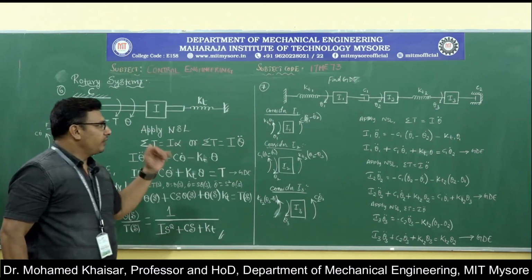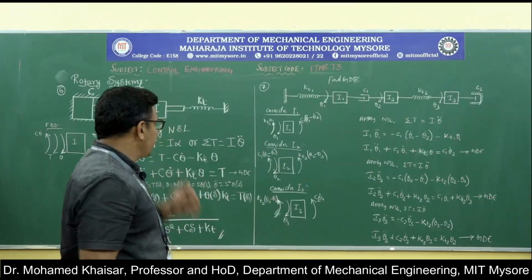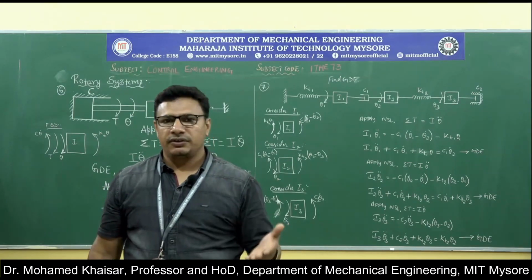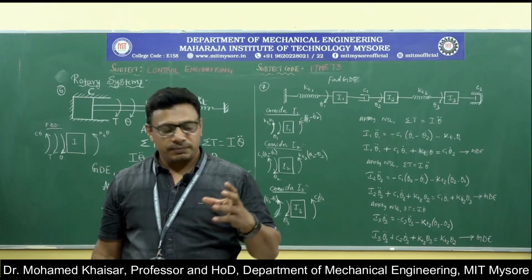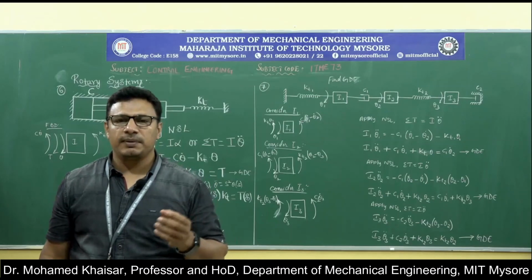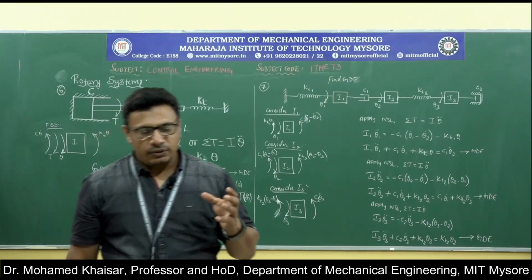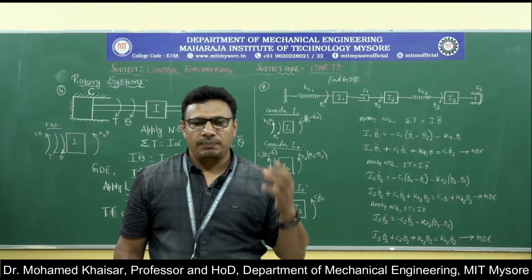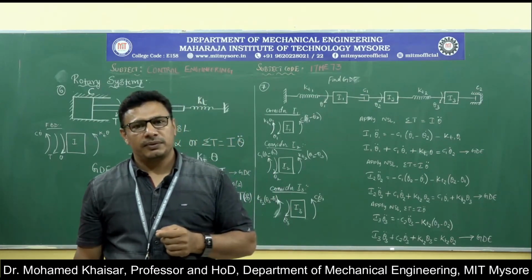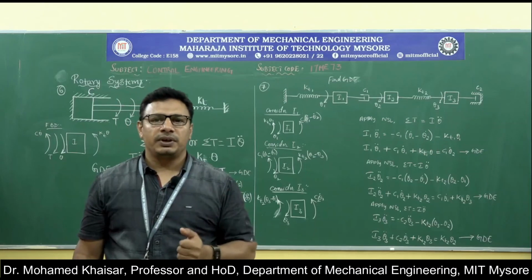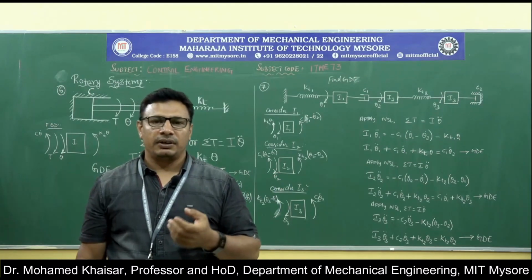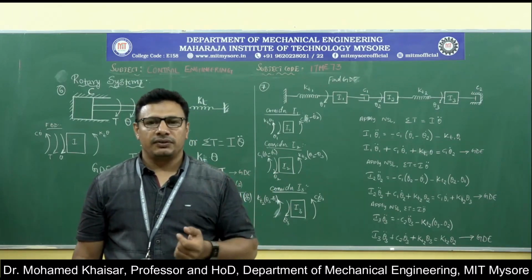So, this is how we have solved as many as about 7 problems in mechanical systems, in both linear systems as well as rotary systems. We went on from the simplest of any linear system, such as a single mass spring mass damper system, wherein we tried to know how to write the functional block diagram. We applied Newton's second law, then we found out the governing differential equation. Then we applied Laplace transformation, whereby the degree of the components of the equation was brought down to single, and then we derived the transfer function. That was with a single mass system.